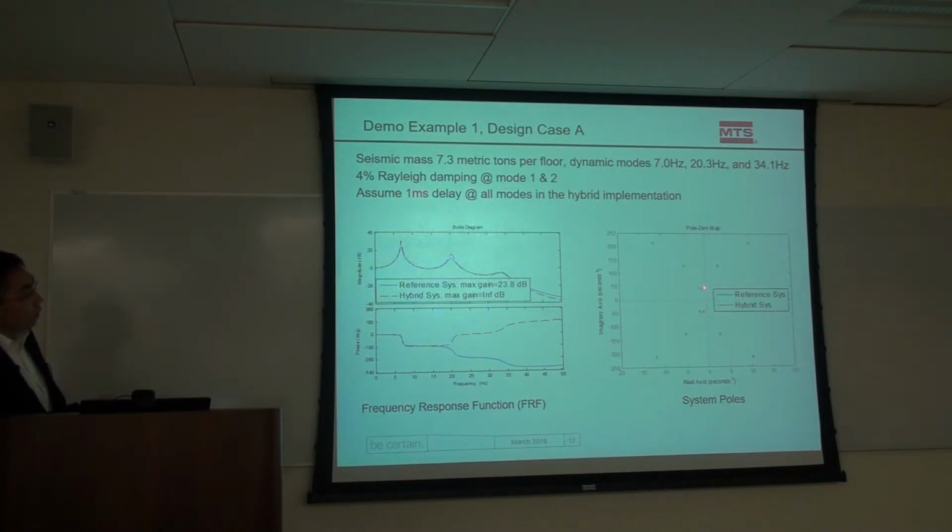The first mode is still stable, although you can notice it shifted to the right half plane. It added negative damping in there. The second and third modes are already on the right half of the plane, so your response will grow exponentially with respect to time. It's pretty much unstable. Whenever you click the button to run the test, it will blow up.